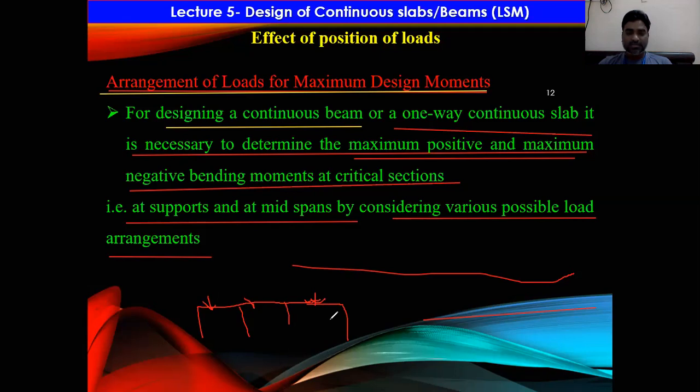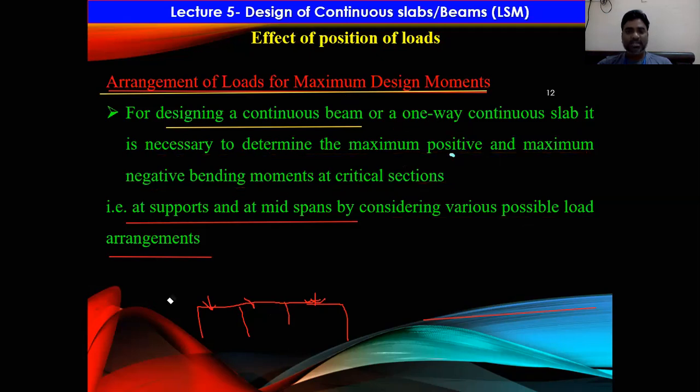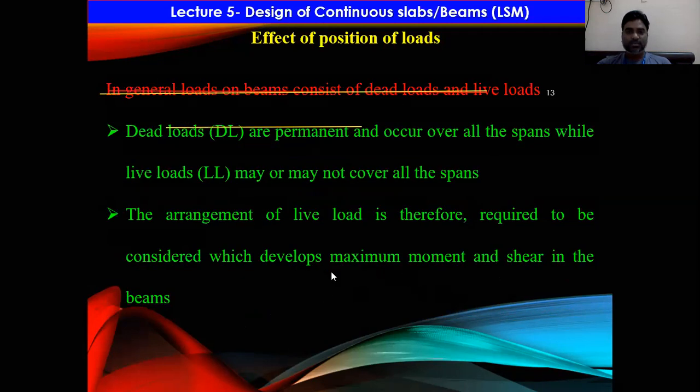See, we cannot say that if you apply total load, then you will get the maximum. It is not like that, right? So we will see all these things while designing continuous beams and slabs, right? So you need to try all these arrangements and compare them and find out the maximum shear forces and bending moments. So that is the arrangement of loads to get the maximum shear forces and bending moments.